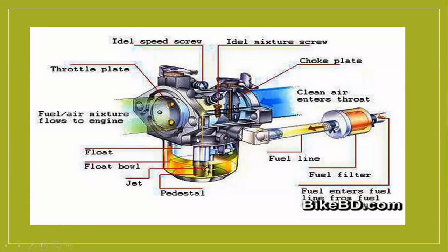Through the jet, the fuel is calibrated and sucked. It is a sucking mechanism. The jet is like a venturi structure. Suction is there, and the jet will suck the fuel from the bowl. A lot of fuel is there, sucked by the jet. They call this a float. The float is a plastic ball or a ball of lighter material.